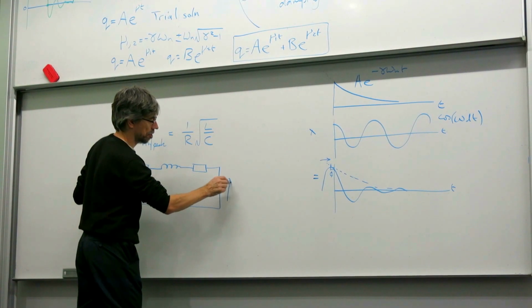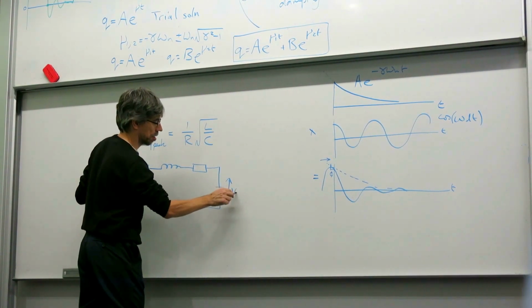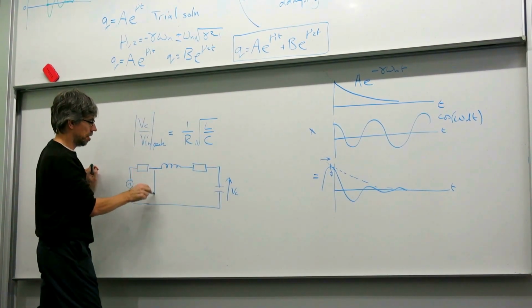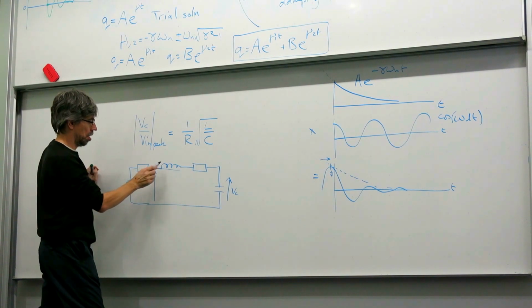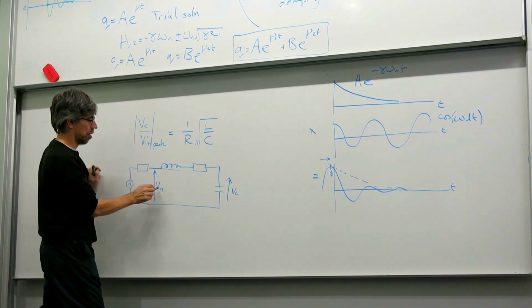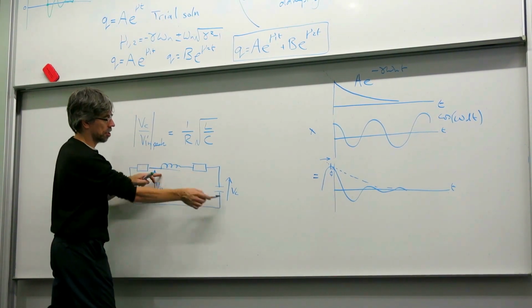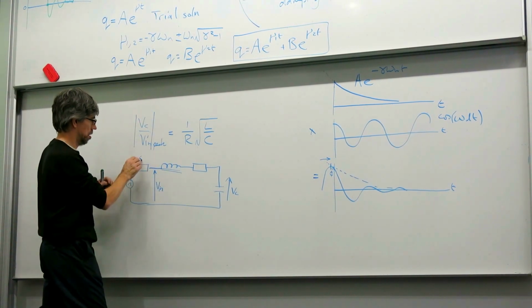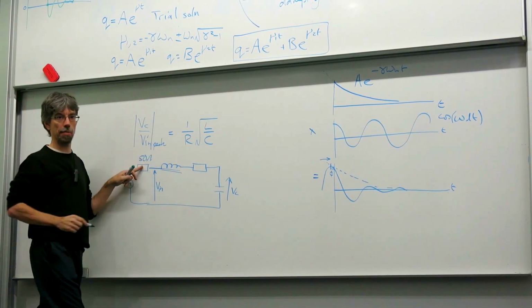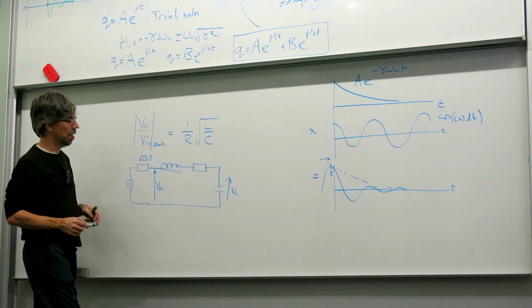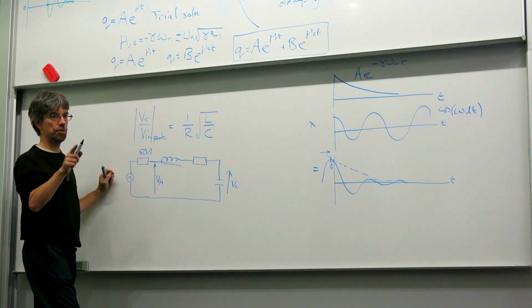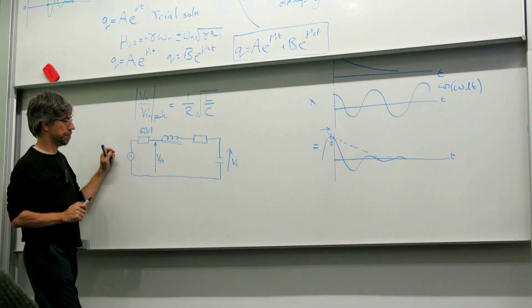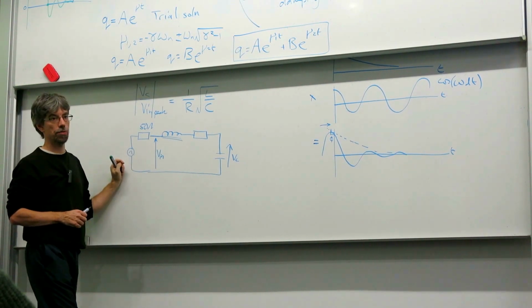So we've got VC, which is the voltage across the capacitor. Vn is the voltage across the inductor, the resistor, and the capacitor. That's the 50 ohm output impedance. So when they're building that equation, it's basically a voltage divider.